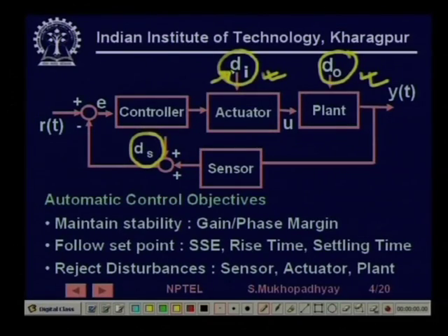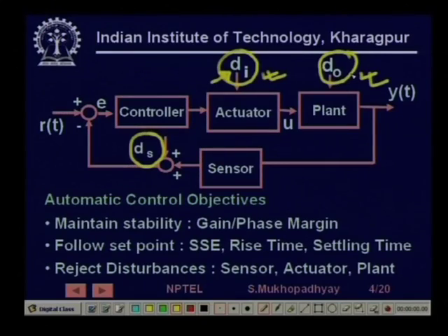Similarly, if you take manufacturing, for example, suppose you are taking rolling. In rolling, you want to control the speed of the rolls and the gap of the rolls. Now, when a metal bar comes and grips the rolls, immediately there is a tremendous torque demand which comes on this. That torque demand depends on a lot of factors. For example, one of the important things on which it depends is the temperature of the bar which is biting into the rolls. So, such things are called load disturbances.